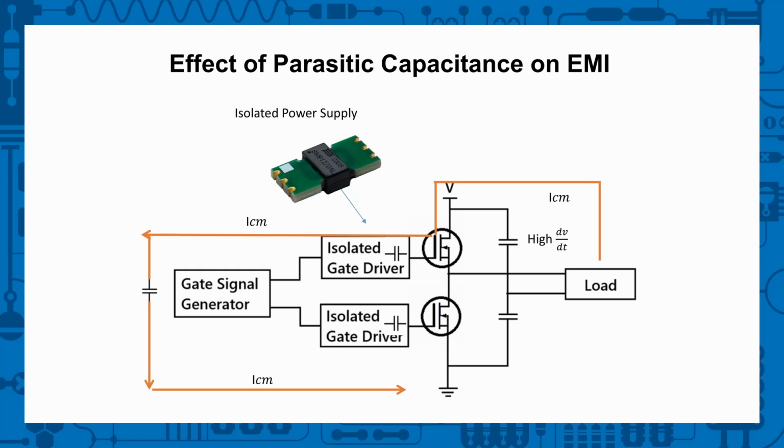So controlling the tolerance there is one thing, but when you have, let's say, a planar design, particularly a very small device like a very small planar transformer, the coplanarity is very good, and then once you have a production line set up, the tolerances in the gaps between the coils are infinitely better than a concentric transformer.